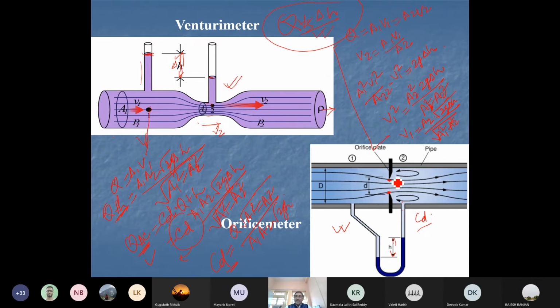You might have seen here, this is not exactly a pipe where we are simply cutting a hole, but it is having a kind of beveling towards the downstream side. And this bevel angle, our cutting angle, varies from 31 degrees to 45 degrees for an orifice plate.